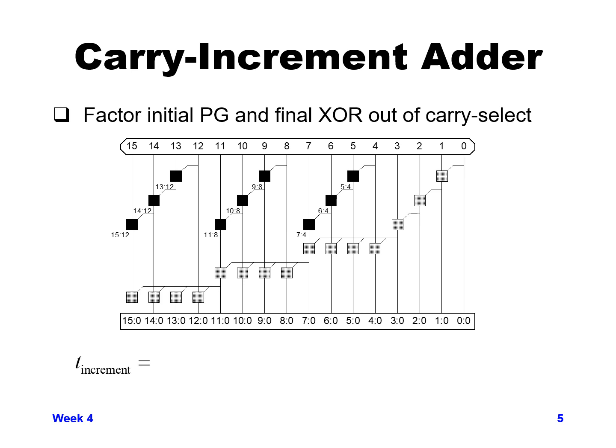So splitting out the logic in that way is what's called a carry increment adder. You share the PG generation for each bit, and then the mux function incorporates the logic for carry in 0 versus carry in 1. And here we can see the delay graph if we did that.